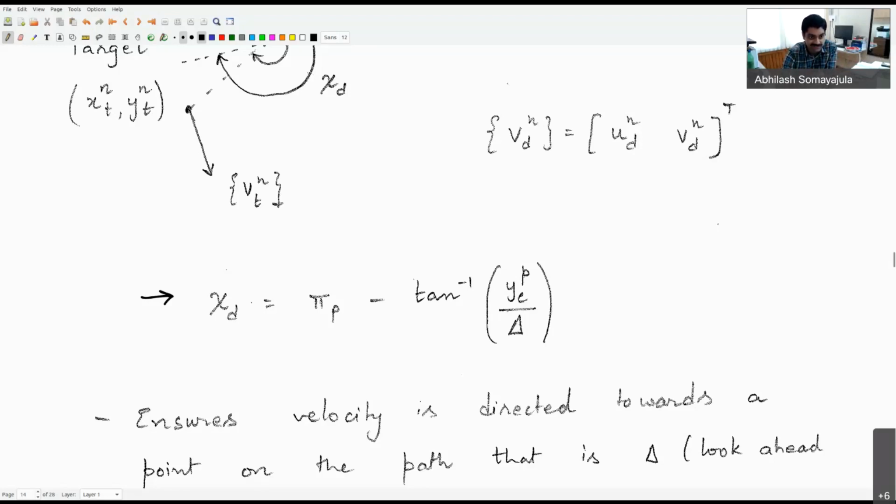Is that making sense? Because it is trying to find the direction between the velocity vector and the true north. If the velocity itself was zero, which direction the velocity would be pointing at would be ambiguous. So we can't define a course angle precisely where the ship does not have a forward speed. Whereas on the contrary, heading angle is always defined, because heading angle is defined with respect to the ship's longitudinal direction. That is always defined whether the boat is moving at forward speed or not.